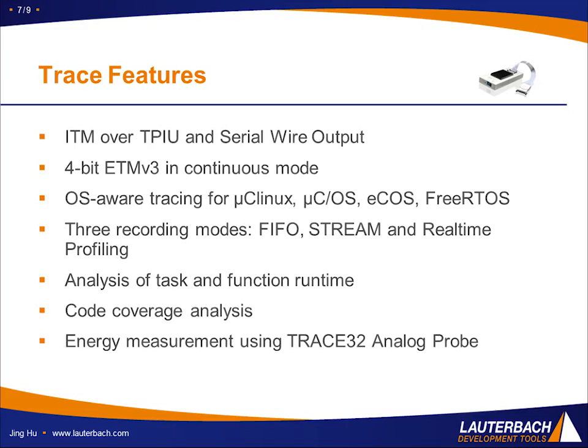FIFO is most commonly used. Stream mode is useful when long-period recording is needed. Real-time profiling is particularly suitable for performing coverage analysis and makes the analysis of tasks and functions at runtime possible. Last but not least, Microtrace is also available for energy measurement using the TRACE32 analog probe.